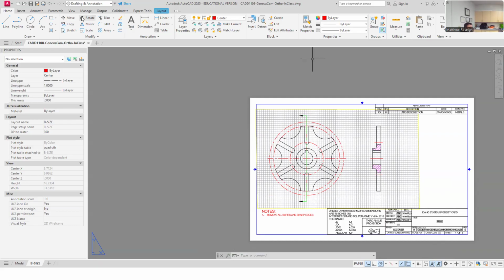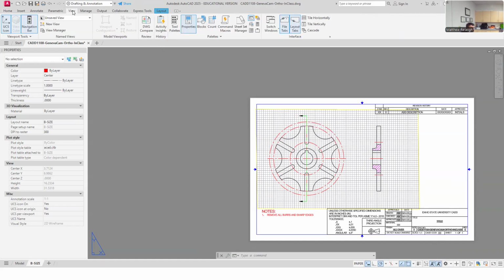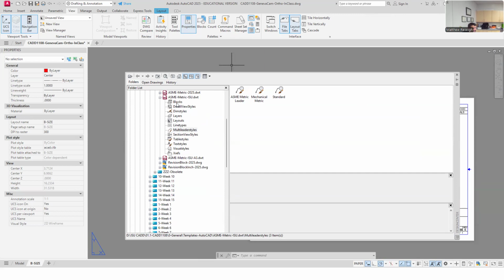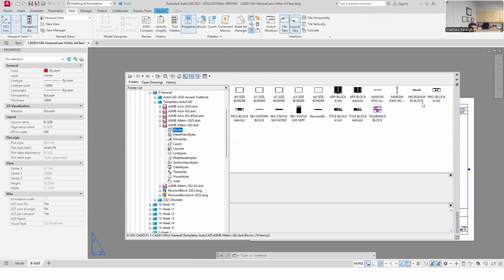So, what I mean is right here, if I needed to use that on another drawing, I just go into my view. When I'm in that other drawing, I can go into the view, and I use the design center a lot to toggle down through where I have it. Any drawing that you would open up, you go to the blocks and you'll have the blocks available to just drag and drop in. I'm not going to drag and drop that, but you can just quickly add anything you've created in one drawing to the other just by using this browser on the design center.